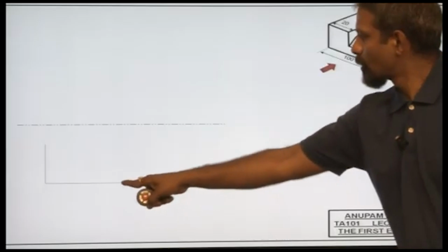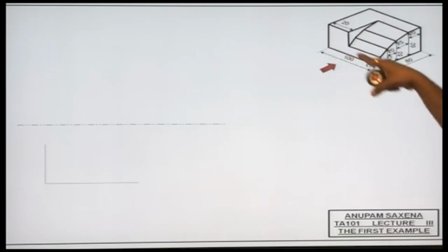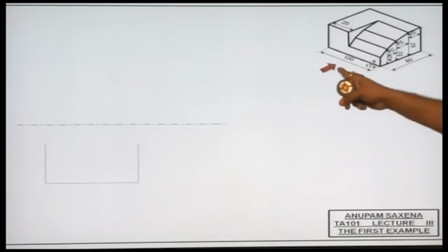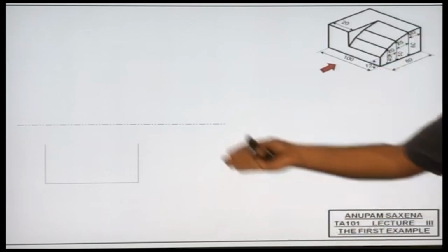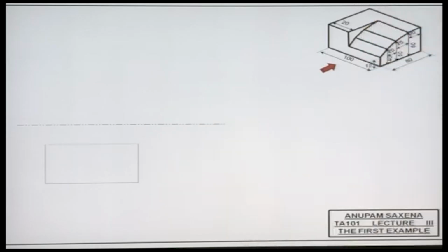Okay, so this horizontal edge would correspond to this edge, the vertical edge would correspond to this edge. If I look at this object along this direction, this entire feature will be represented via this edge, and of course there will be a horizontal edge, this guy here. Always a nice idea to start with the bounding boxes in the corresponding view.